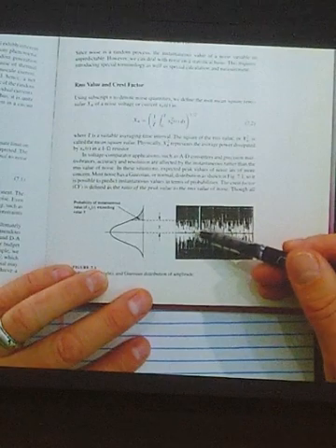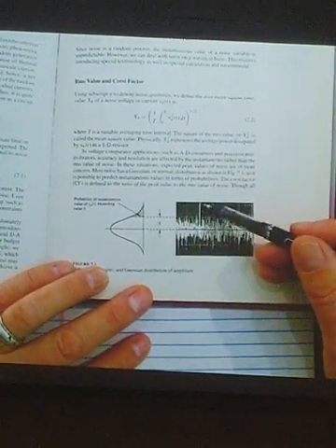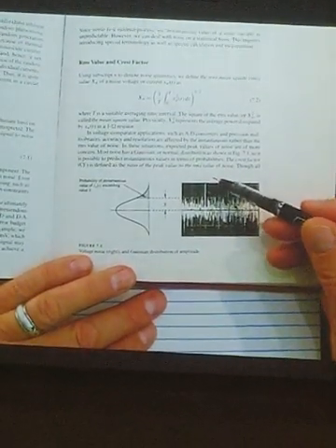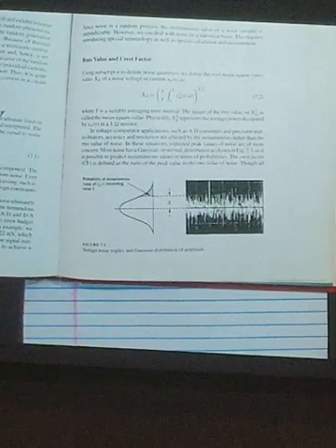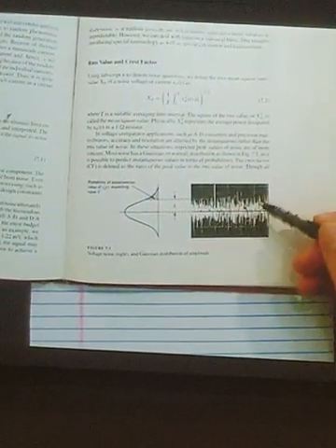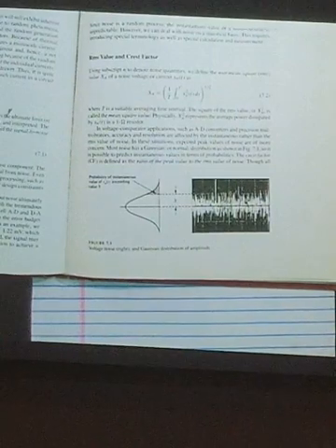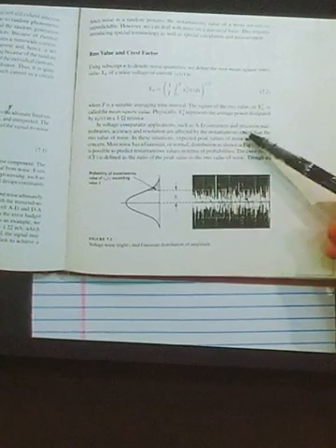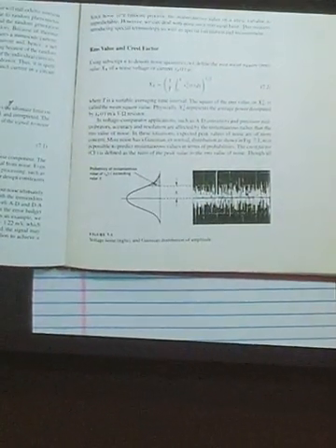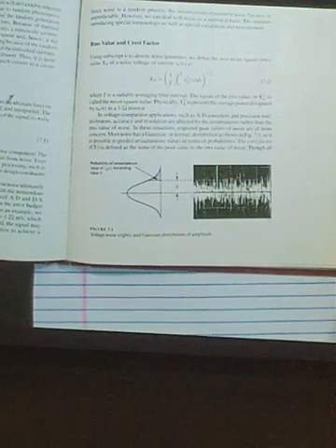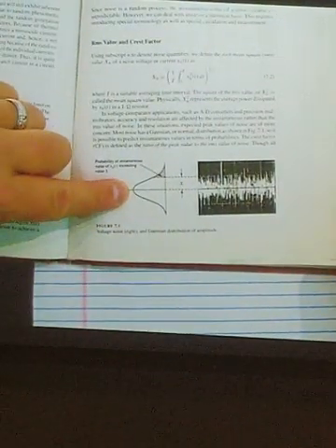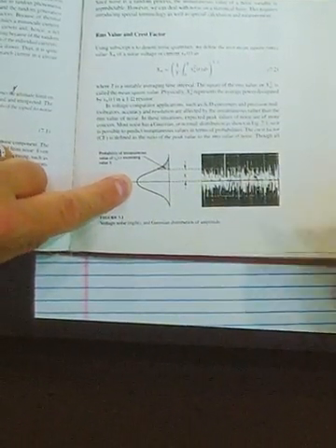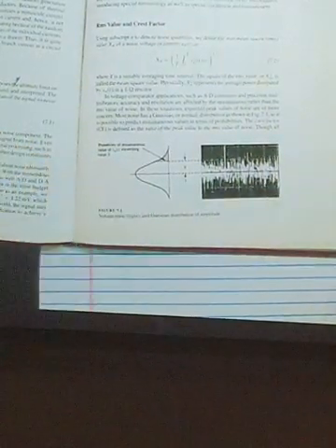It occasionally stays bounded, but there's a finite chance that you can get just about anything out of that. Now, clearly, ultimately, this is power supply limited, but we're typically talking about signals that are 100 microvolts or less here. So, for all practical purposes, you can see there's a finite probability that a voltage spike of any particular amplitude can occur. And in fact, we assume that it's Gaussian, okay? So we assume that the distribution of voltage values is Gaussian.